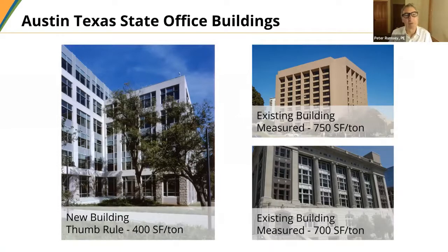Smaller chillers, smaller pipes, smaller electrical system, smaller ductwork. Everything was smaller because we right-sized the system. And I want you to remember this for your career as a professional: right-sizing is really important. It's very easy to be lazy and oversize everything.